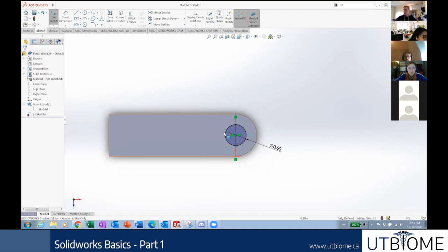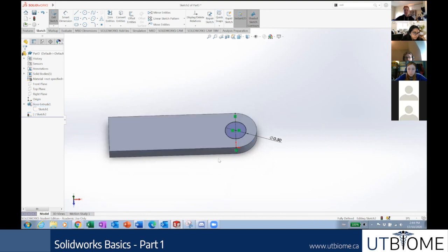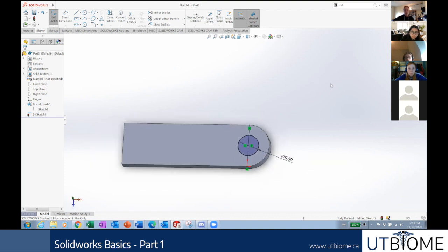And so once you do that, it should be fully defined and ready to cut. So I'll give you 2 minutes now, until 2:45, just to catch up. Remember what we did before: we started by drawing on the top face. We right clicked, started a sketch, drew a circle off to the side, then drew a center line, dimensioned our circle for a diameter of 0.5, and then put the center of our circle on the midpoint of the line.